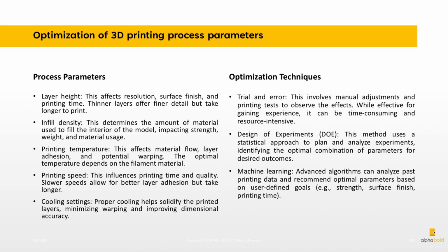Printing speed. This influences printing time and quality. Slower speeds allow for better layer adhesion, but take longer. Cooling settings. Proper cooling helps solidify the printed layers, minimizing warping and improving dimensional accuracy.